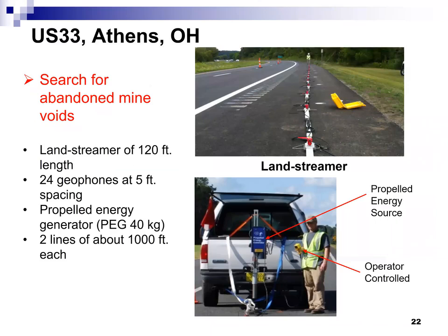So here we did it on the shoulder of the pavement of the road. Here we use a land streamer geophone. Simply, we just put the geophone on top of the metal tripod, so we don't have to couple the geophone into the pavement material. We tie all 24 geophones together so that we can move quickly along the road.